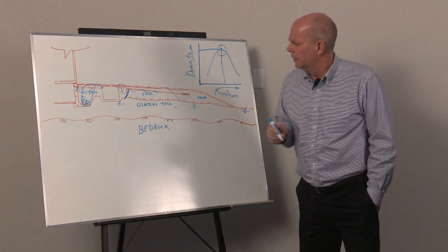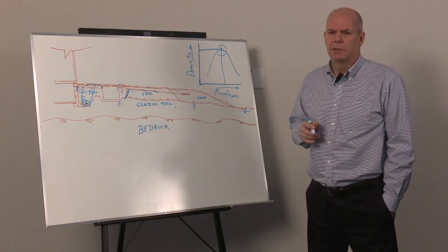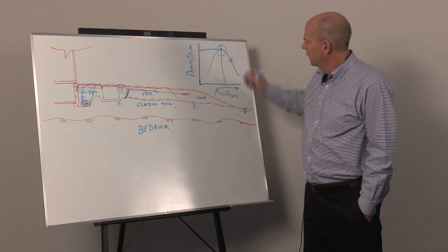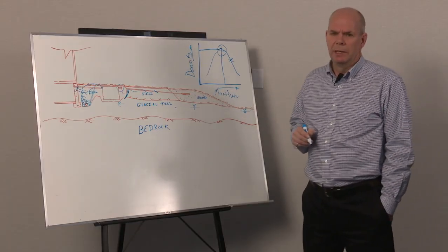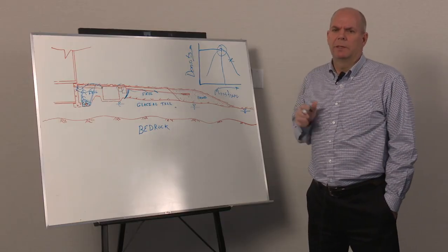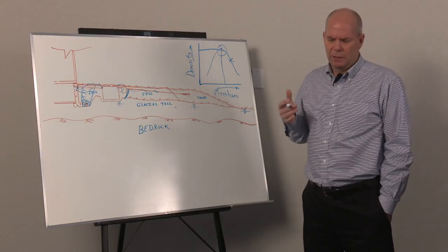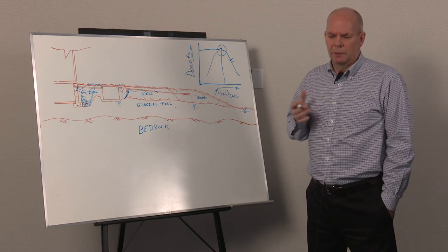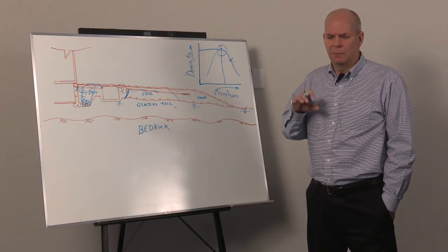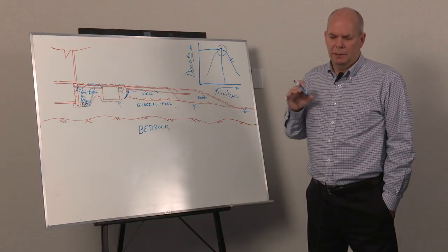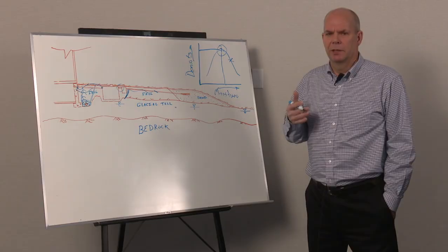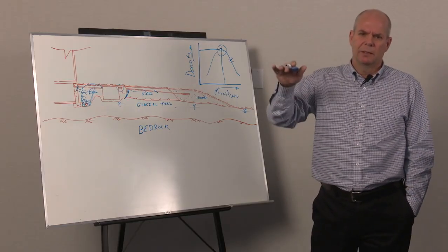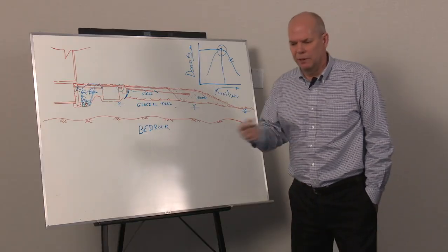Another issue that can happen with these materials is trucking to the site and on the site. In the clay tills, when the moisture content gets elevated, and even in some of the sandy, silty sand tills, you will get a lot of movement of the material. You've probably seen it from repeated trafficking. What happens, especially in the clays, is you build up what's called pore pressure within the soil itself. The weight of the truck is being taken by the water in the soil, and because of the low permeability of the clay, it doesn't let that pressure dissipate. So it keeps adding and adding under repeated loads, and then all of a sudden you get big deformations starting to happen, big wavy deflections in the subgrade that you're hauling on.